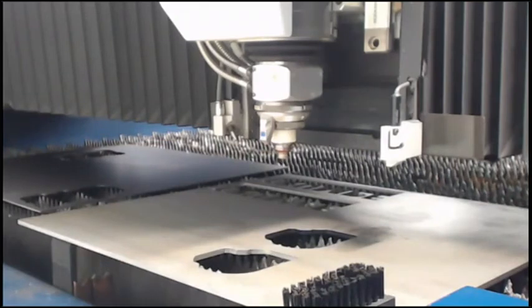Generally, high speed is always the ideal way to go, but if you have a limited number of sleeves, or when people are running really high production volumes, unmanned operations three shifts a day, sometimes they prefer high speed because they don't have to deal with the sleeves. Usually you would have multiple whole bodies inside the nozzle changer. You can change the sleeves manually by yourself, but the machine can't change the sleeves by itself. It can only change the whole nozzle, so you would have to buy the whole assembly multiple times that way. So it depends on what your production environment looks like.